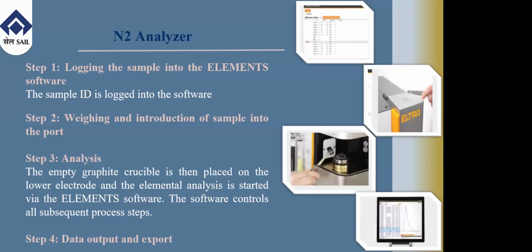For nitrogen, we measure the content using thermal conductivity detectors, because we already have CRM samples of nitrogen. We know how much the thermal conductivity changes based on the nitrogen concentration, and by recalculating it, we get the nitrogen percentage. Finally, after the analysis, we get the data and export it into a LIMS.